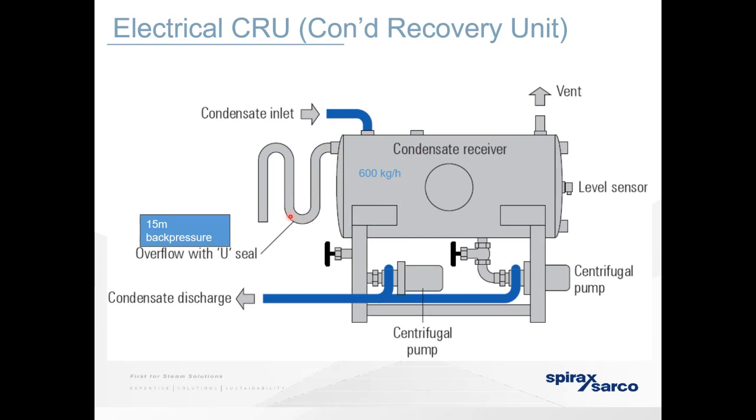If you see steam coming out this pipe, it can be one of two things. Either the water seal that's in here has been removed, so there's no longer a back pressure to stop that steam venting through the overflow, or, if it continuously happens even after replacing the water seal, this pipe isn't long enough. As a general rule, we would say that this comes down to just above the floor, and then out, just to increase that back pressure.